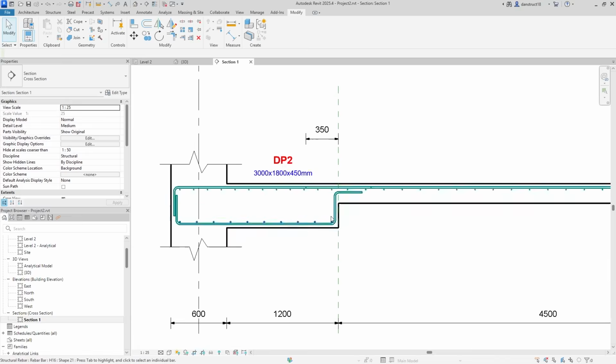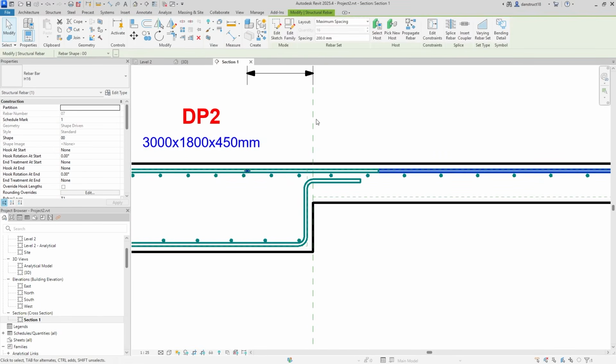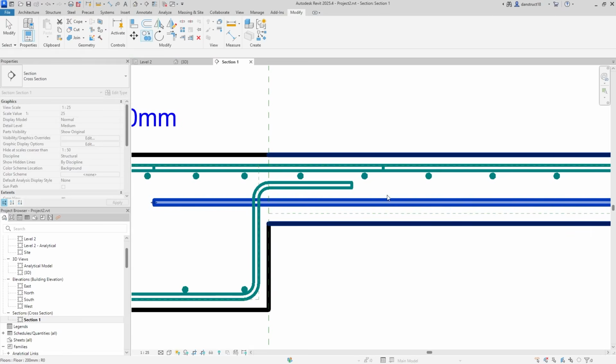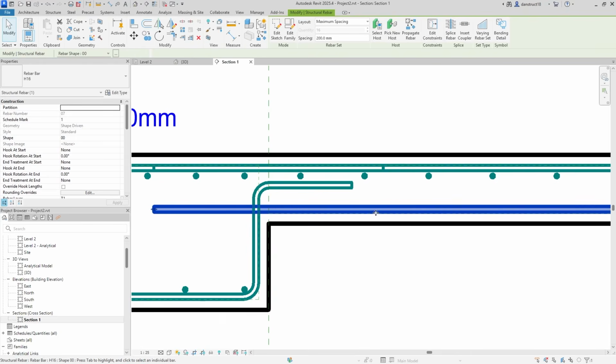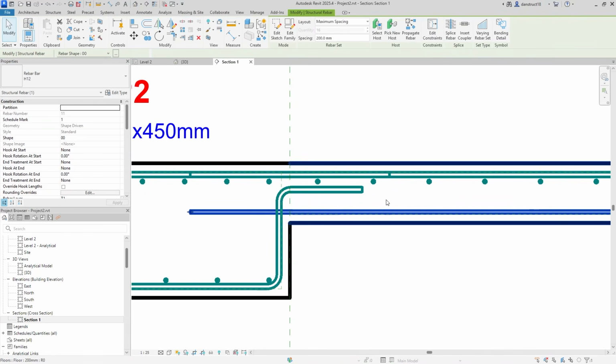All right, good. Now let's place the B1 reinforcements. I'm going to select this one and copy it. I'll click on copy, then click here and paste. I'm going to use my arrow key to nudge it to the bottom, just like this, so it sits just before the cover. And I'm going to change this to a 12 bar. Then I'll nudge it down a bit more.